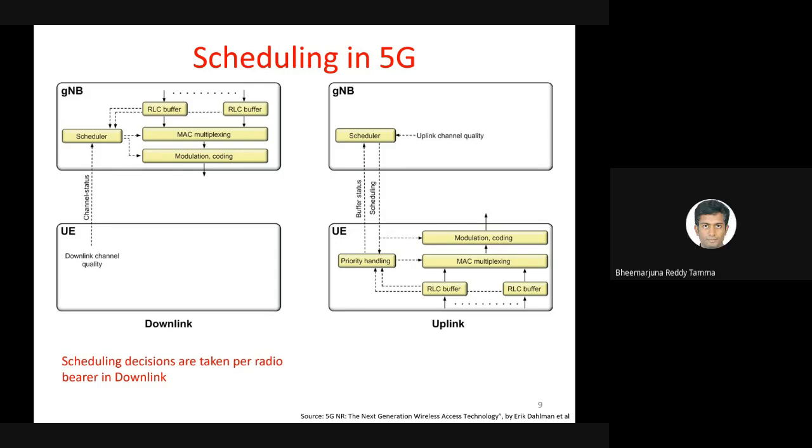Yes. So to simplify the whole process, the base station uses something called DMRS, the demodulation reference signal, in the case of downlink. And in the case of uplink, they use something called SRS, the sounding reference signal. Basically, it is like a predetermined signal that is emitted by the base station periodically. And in the case of uplink, the sounding reference signal is emitted by your handset at certain time intervals. The purpose of these reference signals, as the name says, is that they are a kind of standard signal that the base station knows and the user equipment knows. Let's say the base station is telling you something that you already know.